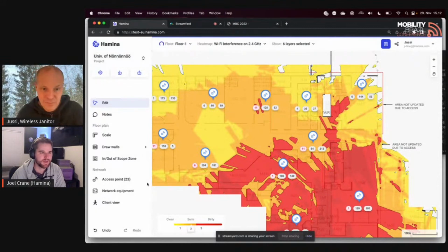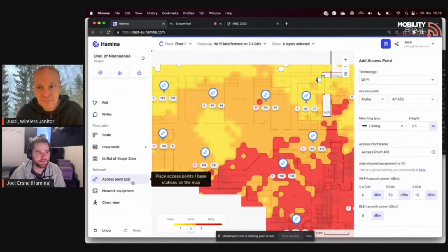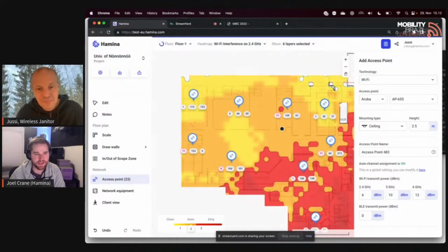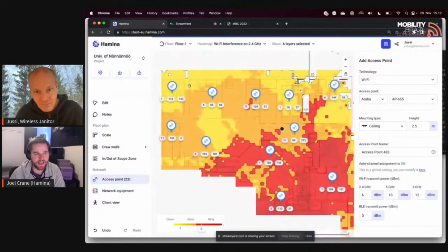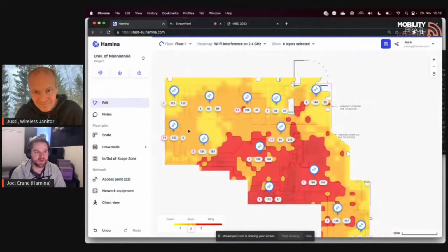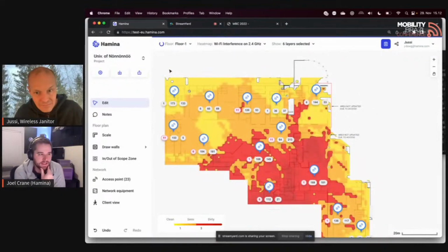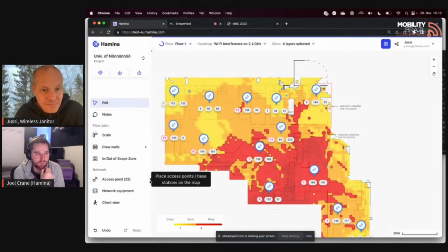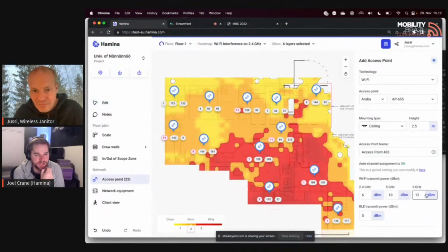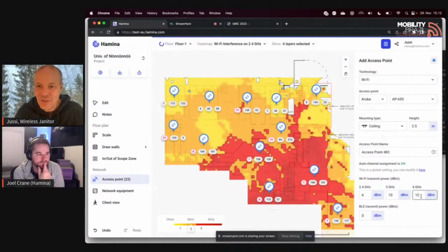Okay. And you see, Korea had some comments about transmit power in the 6 gigahertz band, and it's one of those things where they asked the question, and 5 seconds later we showed it on screen and it was answered. But are you, like me, finding that just a couple dB more in the 6 gigahertz band is enough for transmit power to achieve pretty similar coverage? Do you tune that around at all? That's the good question here.